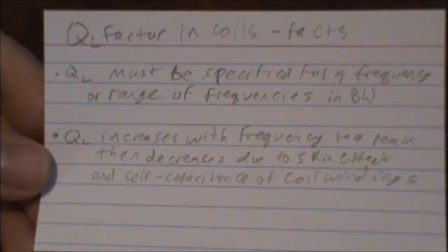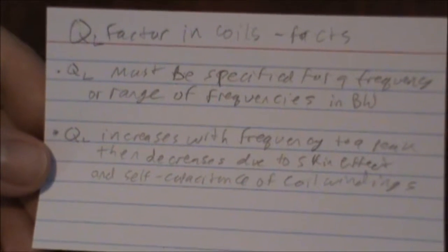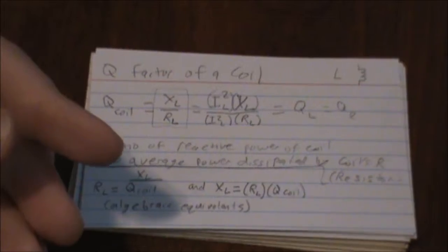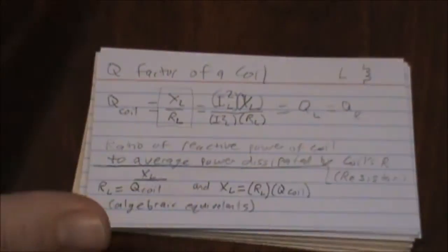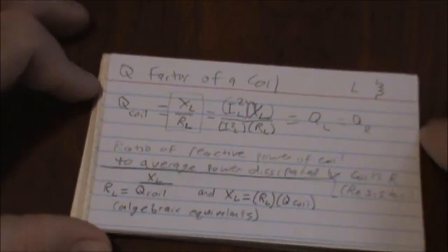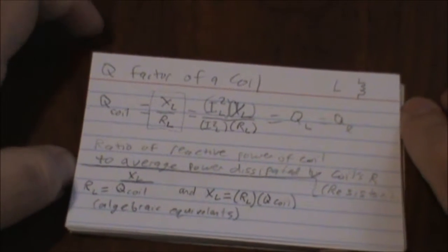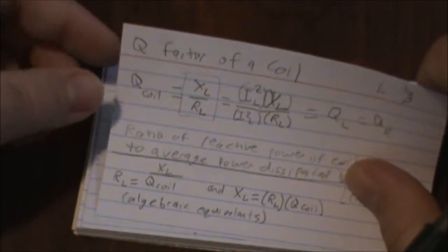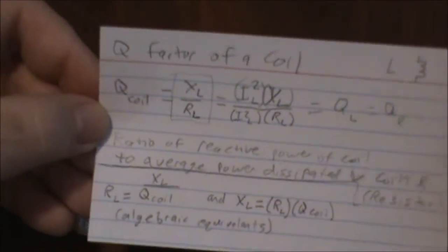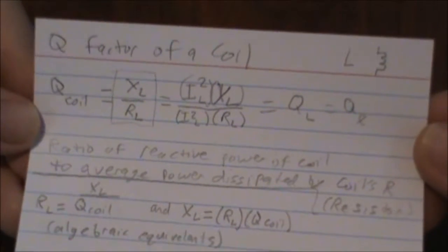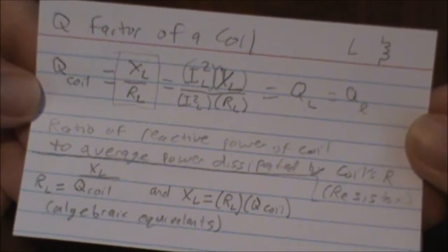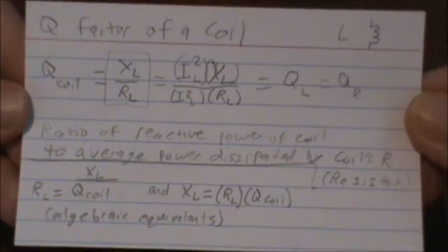That means just the outer part of the conductor is going to have your current through it, which is why we use copper pipe when building Tesla coil primaries, because only that outer part towards the circumference of the material is used. You can use solid wire, you just won't use all of it at Tesla coil frequencies, say 100 to 250, maybe even 300 kilohertz, but sometimes it drops off at megahertz.